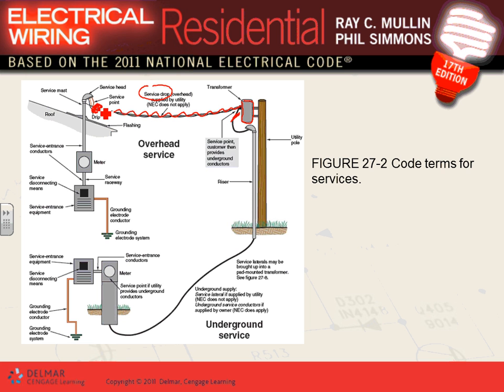Now, if you're going underground, my service point is right in here where you tie to the transformers. Then what do you own? The utilities will own and operate this area, and this cable here. All this conduit, you own and operate, all the way, and from here you own and operate this one. All this system you own and operate. Can I have a thumbs up, Chad? We know what we own and operate versus what the utility owns and operates.